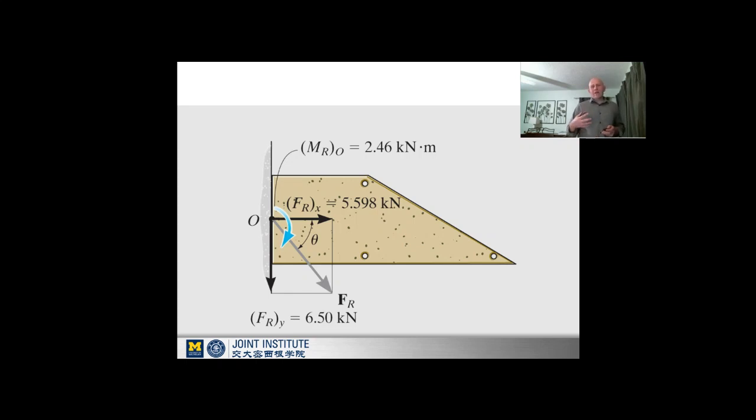So if you go through that summation, you'd end up with a moment applied, and then you could take that and show all of the forces transmitted at point O, and that would be the force resultant. That's the total force: summation of all X, summation of all Y components, shown in their components here. And then you can calculate the angle by using a tangent, and you can see which angle this force resultant is from the horizontal or vertical. And then you can also do R cross F to calculate the moment resultant.